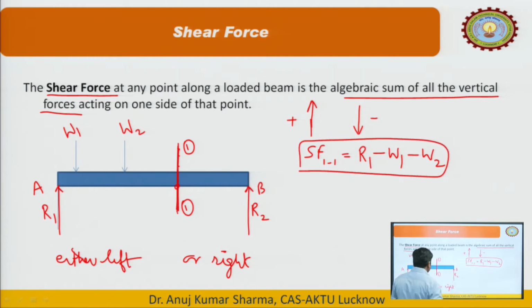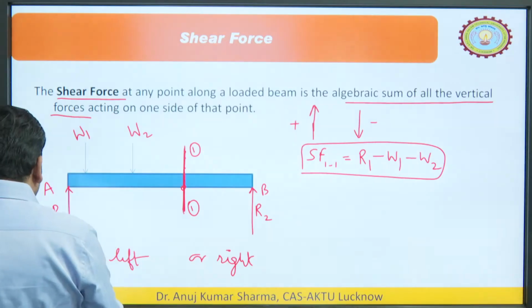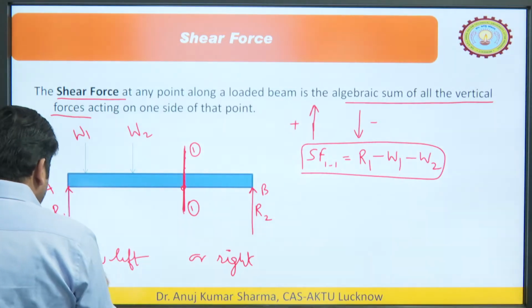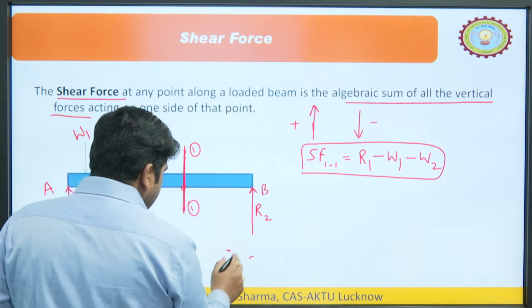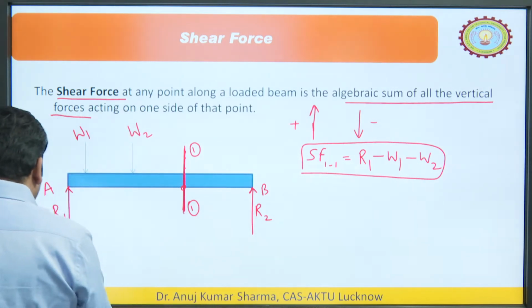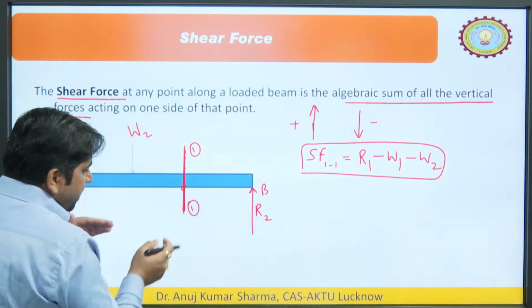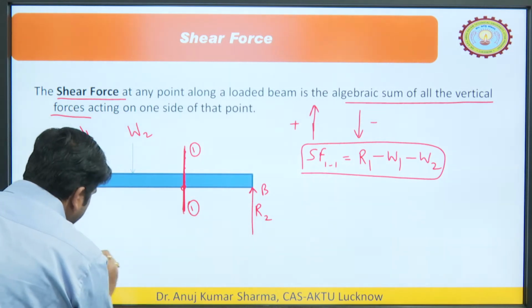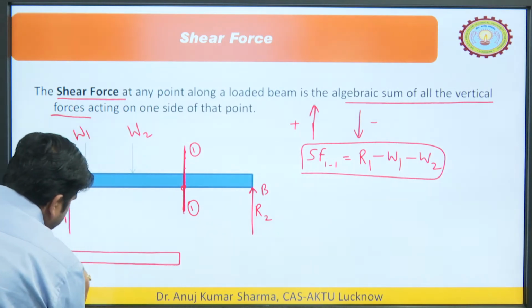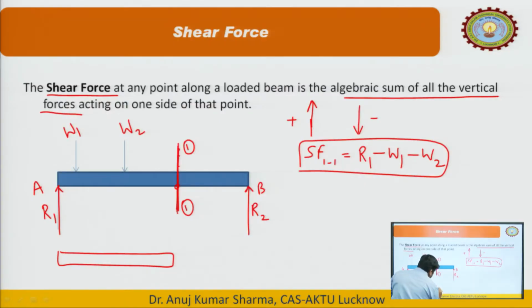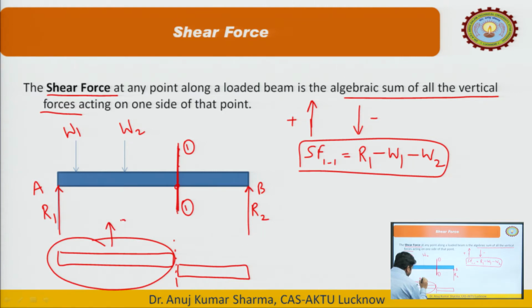So, what will this shear force do? This shear force will definitely help in finding out the shearing of this beam. How can we calculate the shearing? Shearing means when we apply this force, due to material failure it may happen here. If we separate the beam at this section into this portion and this portion, the net force, the overall force acting here, is the shear force.